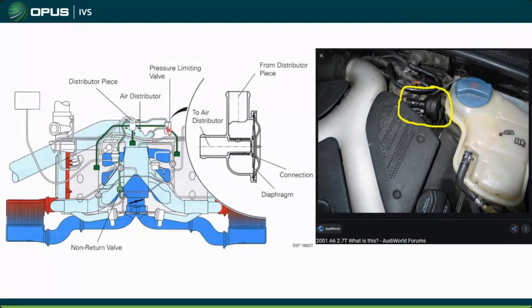And these systems I have seen, as they age, all of these hoses and pressure regulating valves really get all gummed up. The additives that are in fuel and oil these days really do a number on these plastics and rubbers, especially the diaphragms.